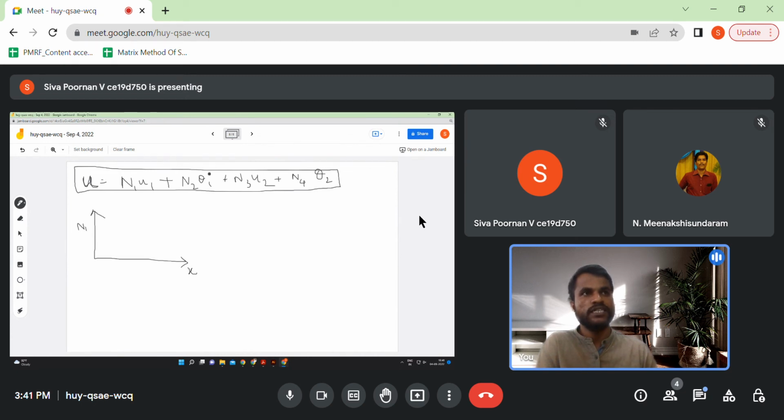If all these quantities become 0 and u1 becomes 1, then N1 is same as displacement, which means that if I give a unit displacement at 1 and theta 1 becomes 0, u2 also becomes 0, theta 2 also becomes 0, then whatever displacement profile I would expect is the N1 function itself. So therefore its variation is the same as the beam deflection problem when I give a unit displacement here. So that's it. This is how it will vary. So this is x2, this is x1.